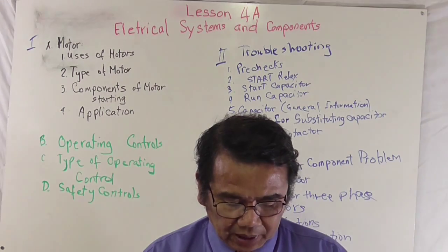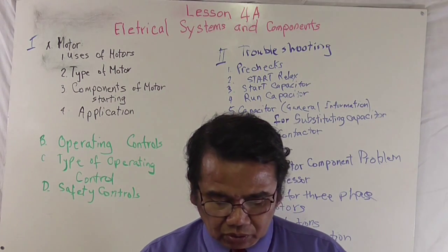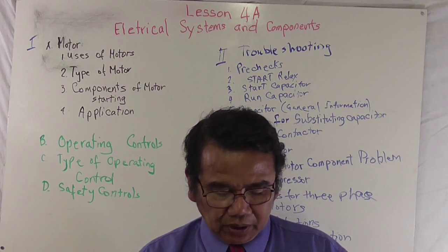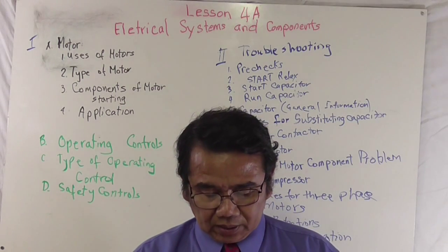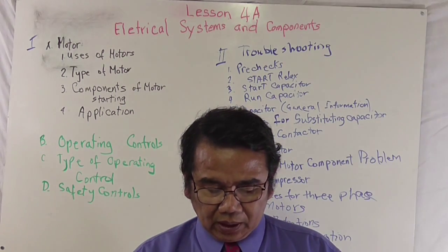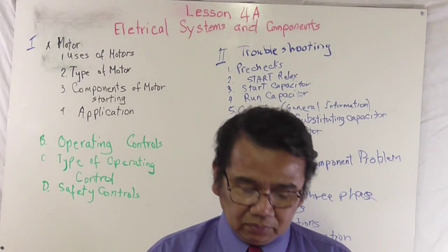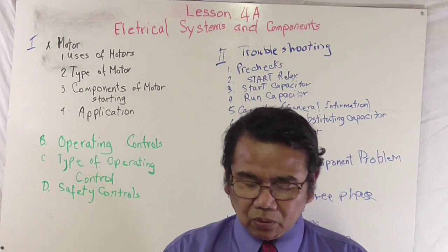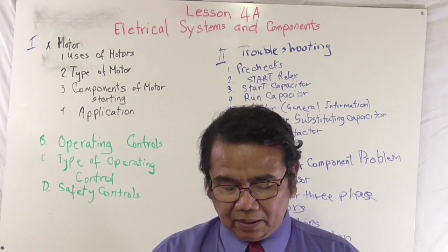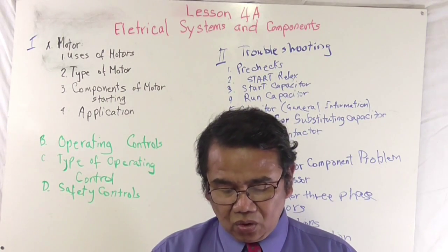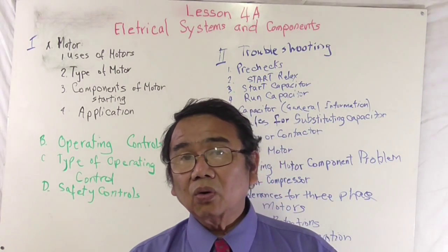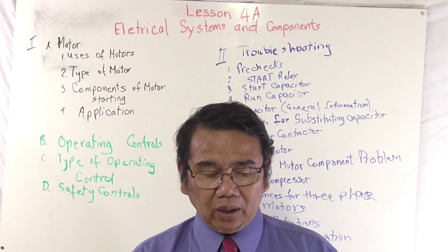And then you have relays or contactors. Okay, relay or contactors will not pull in, no harm. Open control contacts, improper wiring, open circuit, burned or open coil.